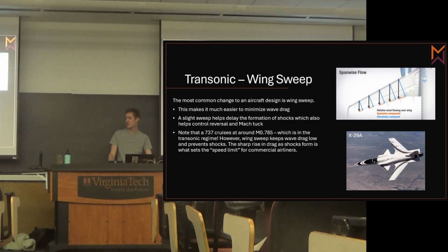Do you remember why? Oh, yeah, it helps with the phugoid mode, which is a very strange thing that happens to planes at relatively high speeds, where they trade altitude for airspeed and pitch at the same time, and they oscillate in a really weird way, and this damps that out faster.